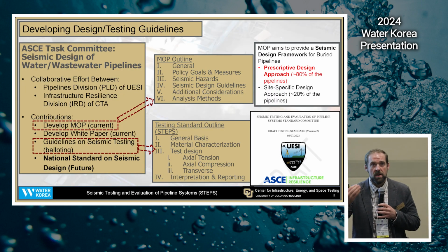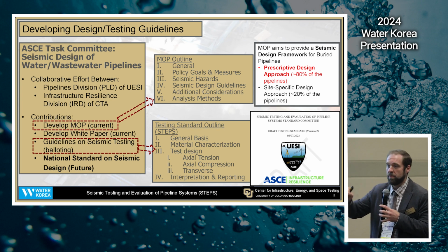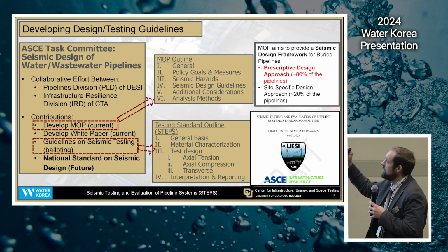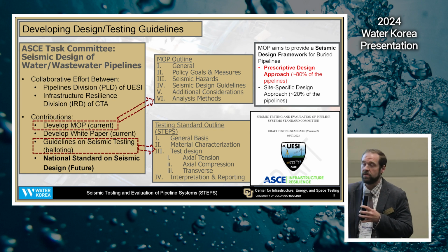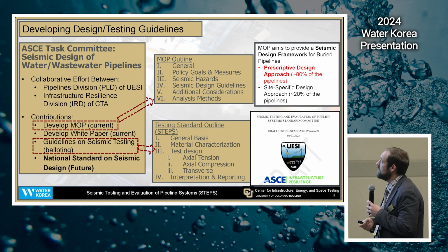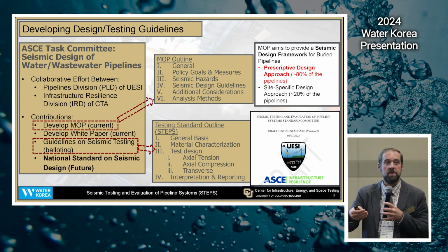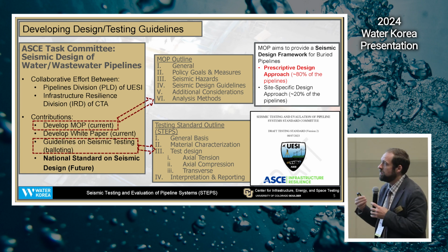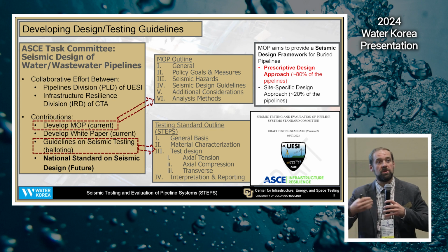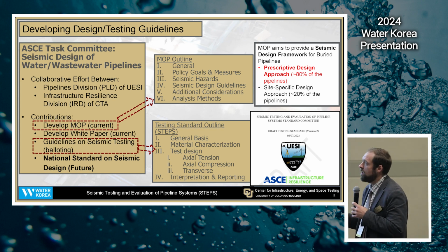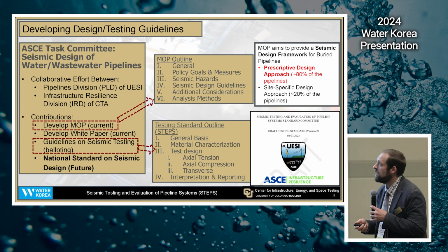So right now, we have a number of excellent ways of looking at the performance of pipeline systems that look a lot at internal loading. So that would be burst testing and long-term pressure, hydraulic-based design. We also look at material performance, but few of these things look at the pipe and the coupling in terms of how it might respond to larger external movements that are imposing a deformation level that would be similar to what a ground movement would cause.